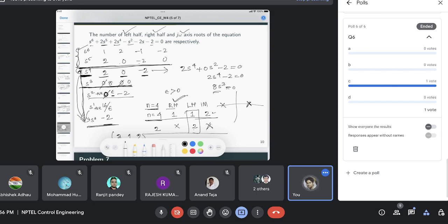So you have 4 poles in the auxiliary polynomial. You then proceed the Routh table with this auxiliary polynomial, take the derivative of it and continue. Whatever analysis comes after this 4th row, where the auxiliary polynomial started, is only for this 4th order auxiliary polynomial.